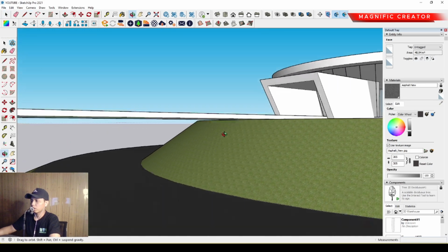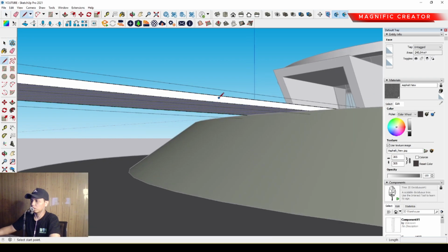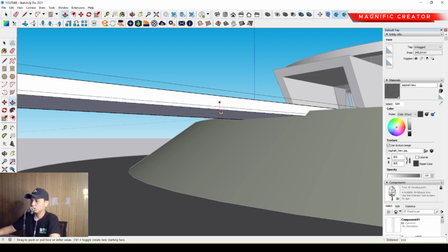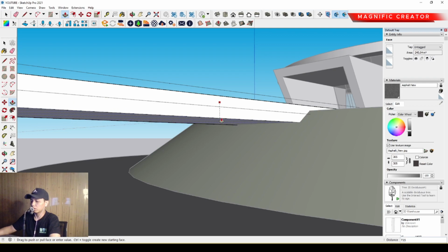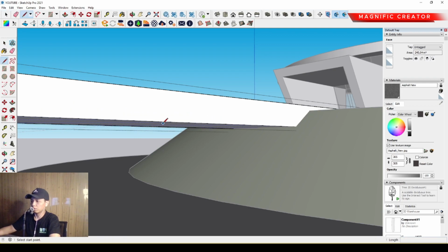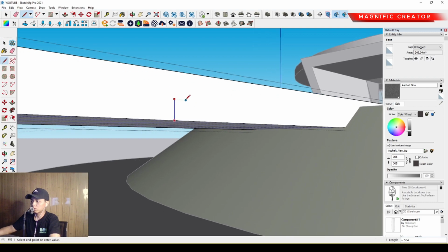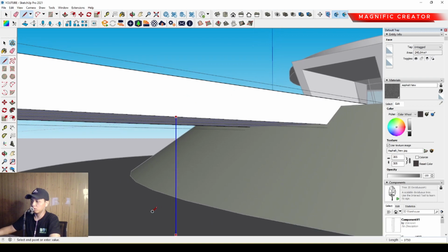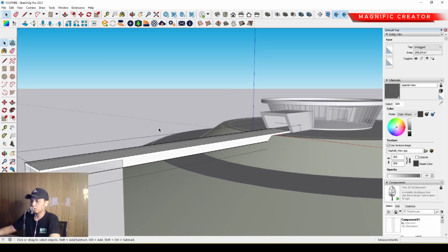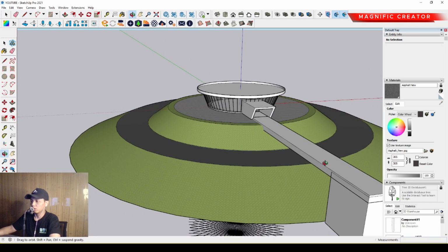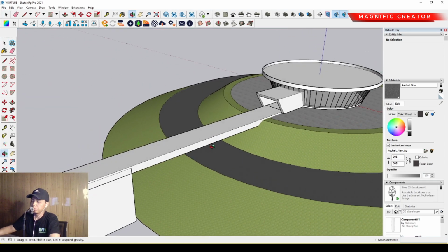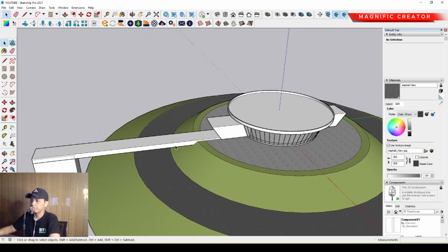So we can, okay, we can set thickness. The current thickness are 300 millimeter, so we can set the thickness 1 meter more. It's just for example. So the clearance for this bottom beam to the floor to the road are 3750 millimeter or 3.75 meter anyway.